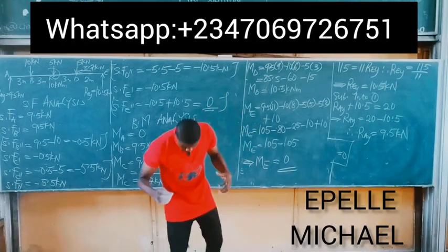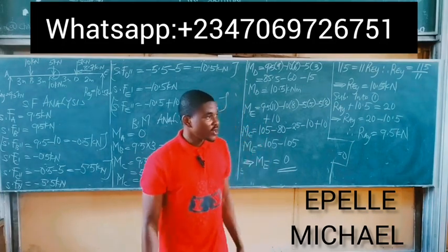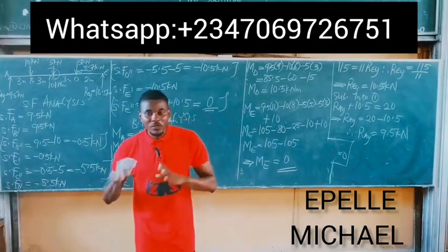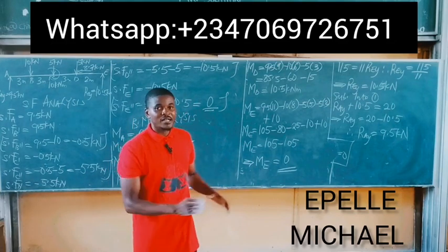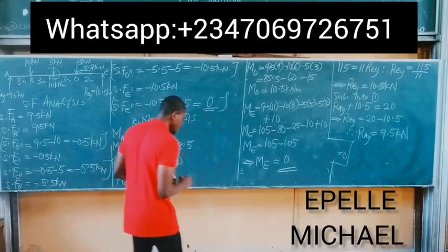At the end of every bending moment analysis, you must always obtain 0 as the answer. So having done with the shear force analysis and bending moment analysis, next thing now is to plot the diagram. Let's do it now and see.